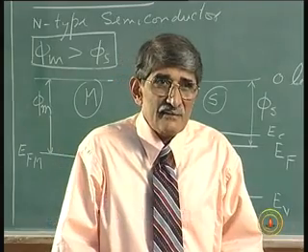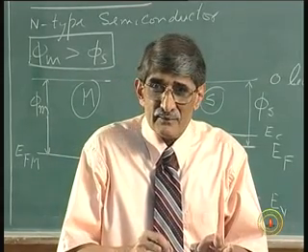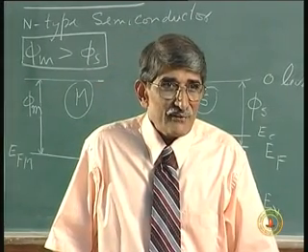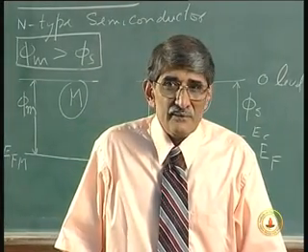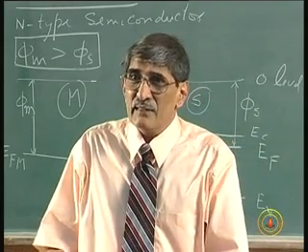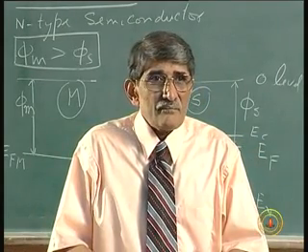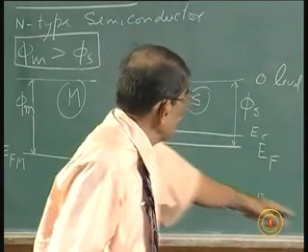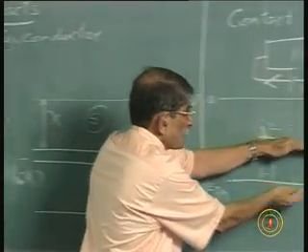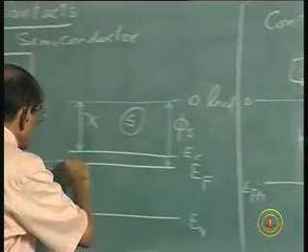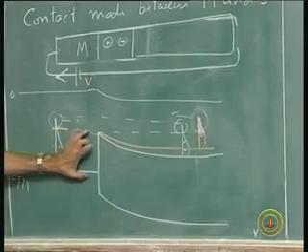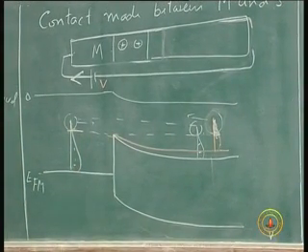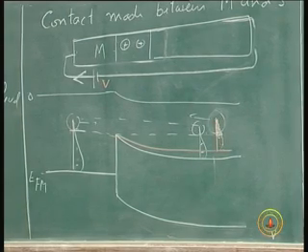But notice, if the difference becomes smaller and smaller, phi b n becomes smaller and smaller, it can become Ohmic contact. That is what I want to say, because it is stretching it beyond a certain point and telling you that phi m less than phi s becomes ohmic. It did not become less than phi s. Still, if this barrier keeps on reducing, that is, if this difference is reduced, so phi b n, okay, that becomes smaller and smaller. So, it becomes leaky. That is why I just deliberately brought this out.